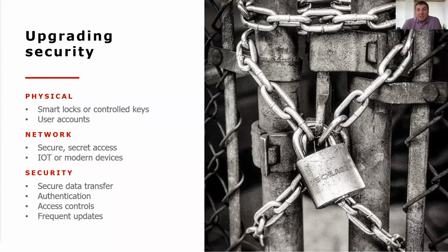Network, same thing. Traffic signal engineer, I am definitely guilty of this. I did not learn a ton about IT in school beyond what I knew on my own, building computers and networks and things like that. But it was self-learned, a lot of it, some reading on Google or whatnot. But essentially, when we deploy all this comm equipment out there in the field, we're not always aware of how it should be implemented. So we've got to make sure that we're either employing the right people or at least getting the right recommendations, that the equipment that's out there has security set up. It's disabling things that shouldn't be, that aren't in use right now. It's restricting access to the network as a whole, not just a signal device, but the whole ecosystem, right?